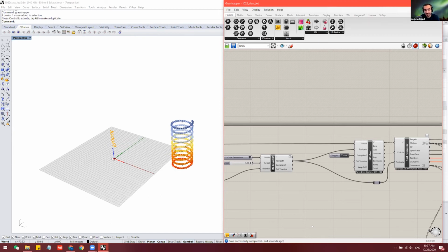So whenever you see that there are singularity issues or reachability issues, try to move your targets, and somehow it may actually solve your problem. Then you can get into more serious solutions like reconfiguration and other stuff.